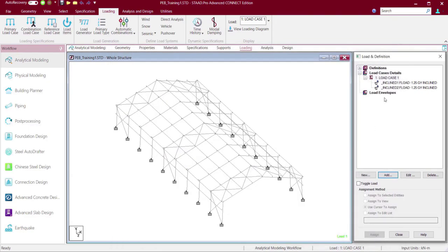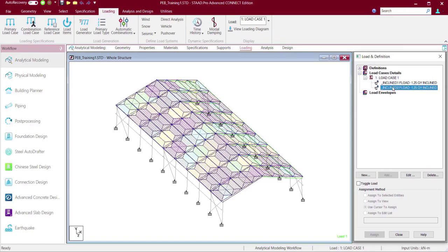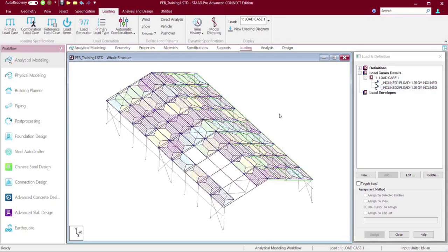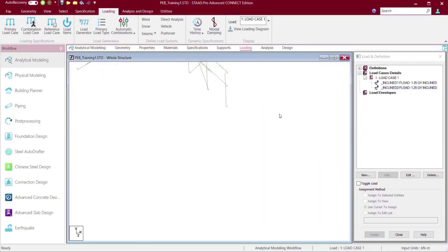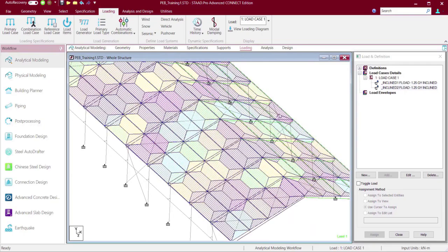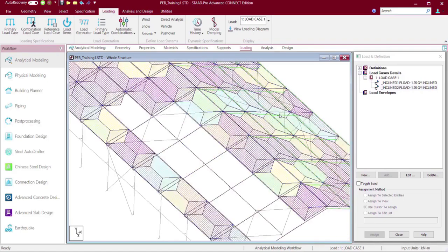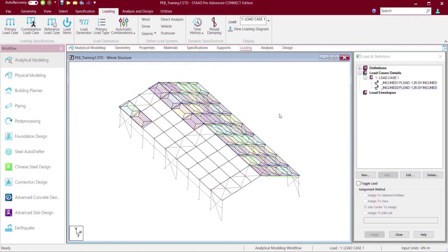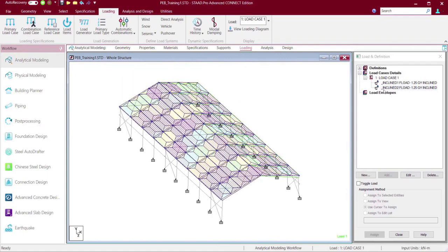So as we are discussing, you can see the patterns of those distributions. It's just like a two-way floor system where the loading of those floor loads is distributed to its nearby or perimeter beams by some geometrical patterns. We call it the tributary distribution system, or some call it the yield line patterns.